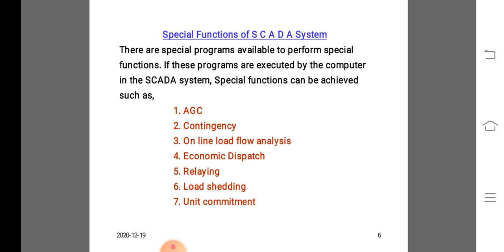Such actions may include, for example, opening or closing of a circuit breaker or switch, modifying a transformer tap setting, raising or lowering generator megawatt output or terminal voltage, switching in or out of a shunt capacitor or inductor, and the starting or stopping of a synchronous condenser.